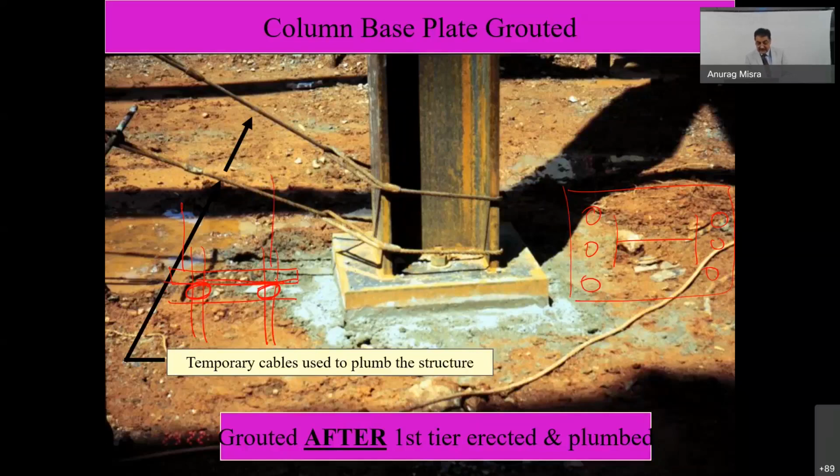Once these are placed in position, the leveling is checked, then you do the bolting on top. Now this space is still empty, so it is then filled with some grout, so that this whole assembly is secured. This is the grout kept here. Normally we go for self-flowing concrete or grout having only 2 to 6 mm aggregates.